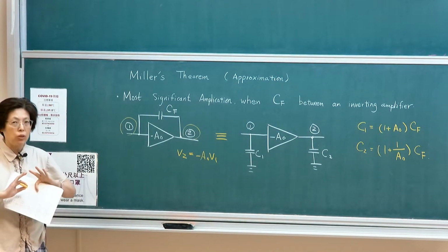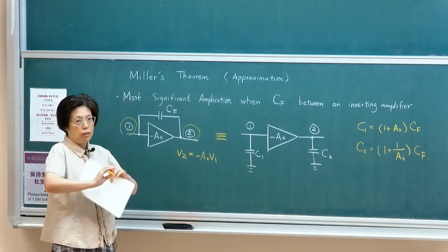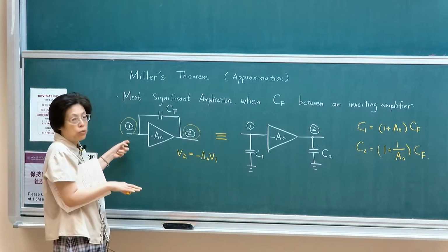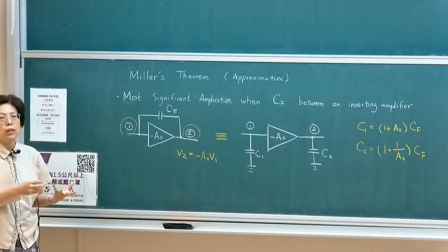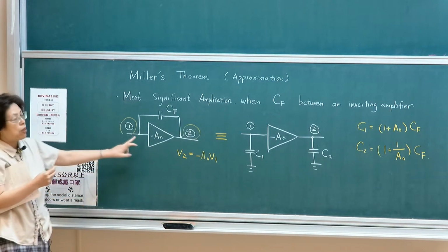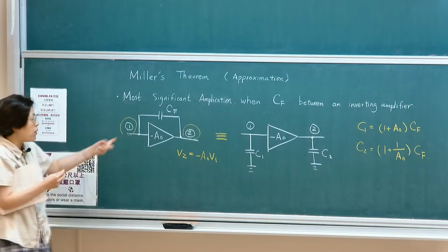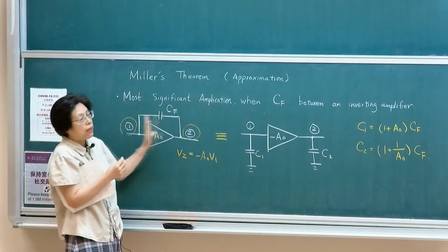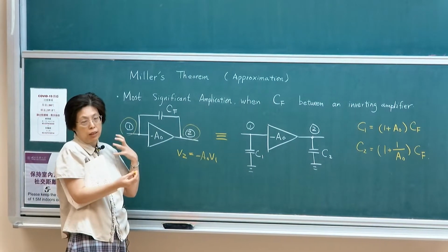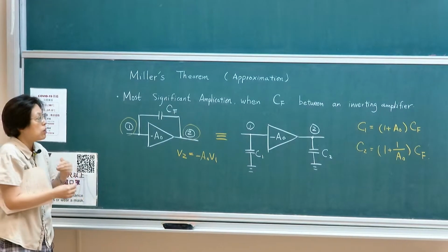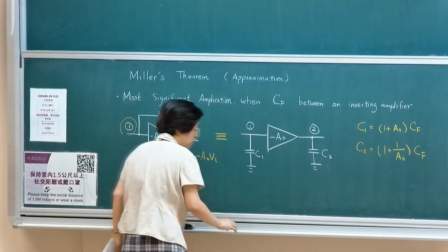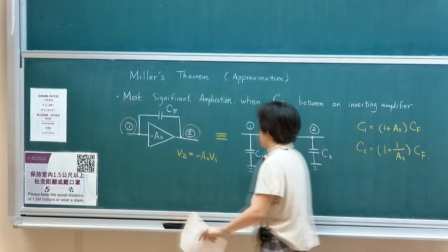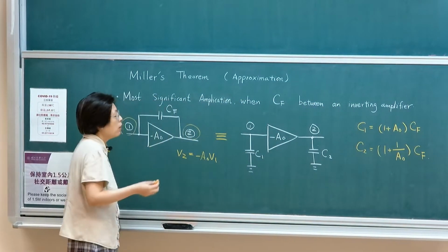So you need to put in more water in order for the potential to rise at V1. That is the main reason you see a particular drag on terminal 1. Therefore, it's very hard to drive it up. So how do we explain these things without having to analyze this cross-coupled interference? We introduce something called effective capacitance. You want to make all your capacitance relative to ground to make this analysis easier.